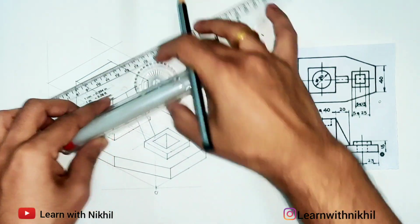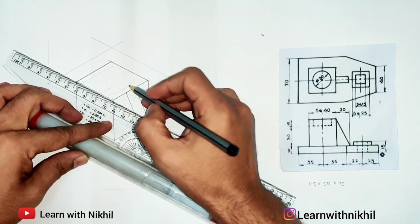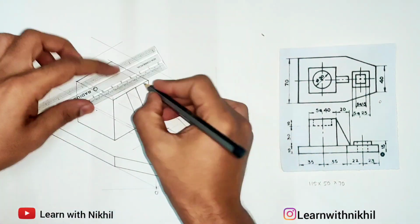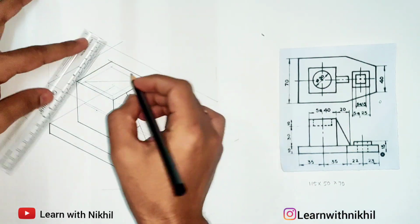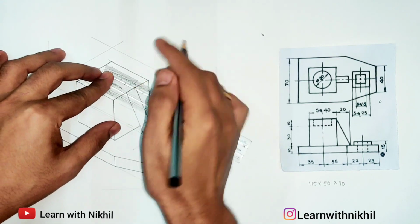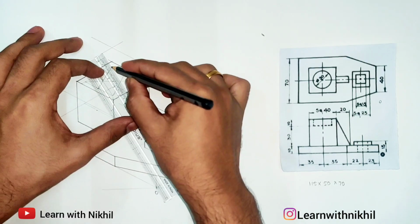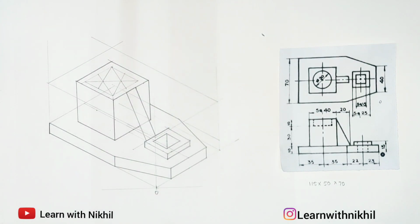As you know the procedure for drawing the circle, we have to create a square of side of its diameter. So drawing it lightly first. So in the center we have created a square of side 30. Now joining the longest diagonal, and from the opposite diagonals joining the center point. This is the procedure you know. Now we got these 4 points. Now through these 4 points we will draw the curves.